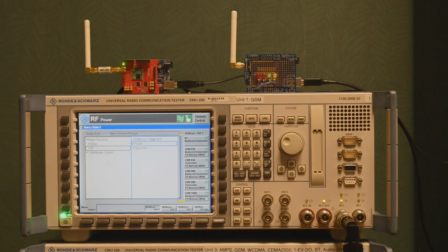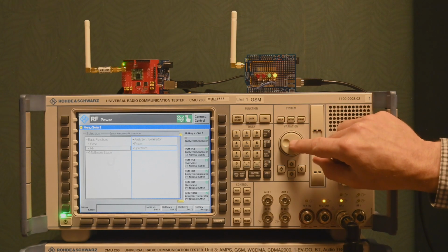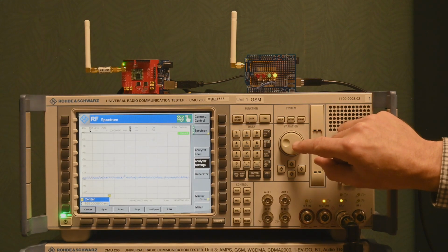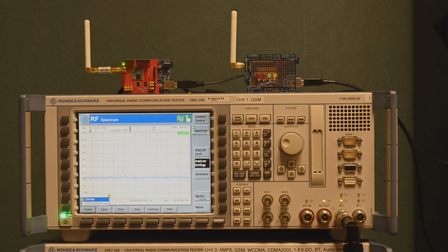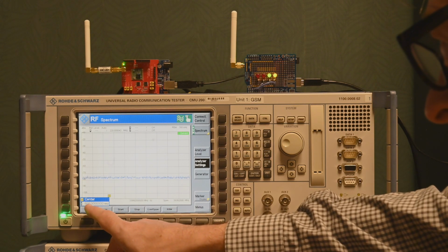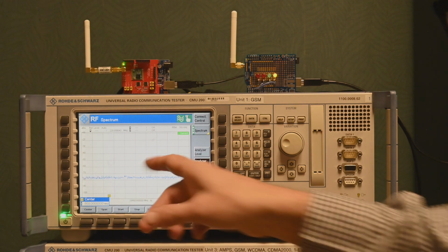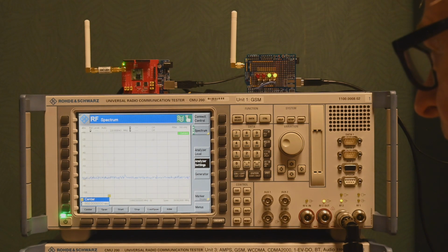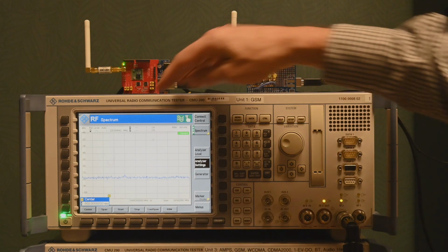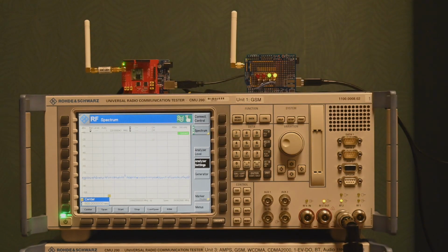And although this episode we're not going to focus basically on the spectrum analyzer, let's take a quick look here. Anyway, we got the spectrum analyzer running here. We got it at 868 megahertz center frequency, and we can see, yeah, with some regularity there is a signal coming in. And if we look well, we might even see that sometimes we got a weaker signal and sometimes a stronger signal coming by.